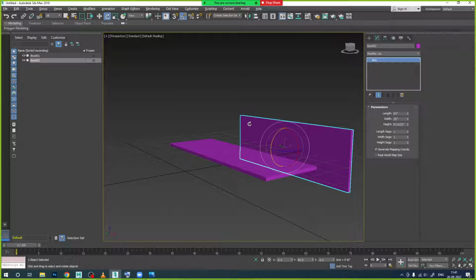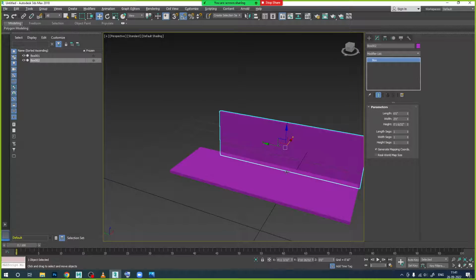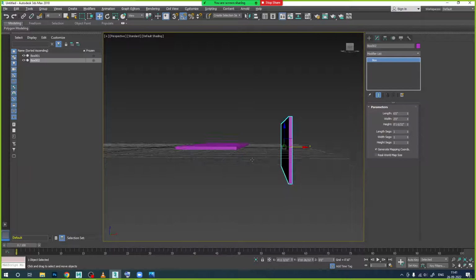Now coming back to the move tool. Now we don't have to change anything, because position and everything is the same, but I want to slightly decrease the depth in this one. That is only for support. It is not a main object. Generally for supporting, we keep a small thin line on it. So in this one I have 0.1, and I'll reduce it to 0.05. Slightly thin, like as if I have taken 1 inch, for the back support I'll take only half inch or quarter inch. Okay, so take this one and try to provide this one over here.